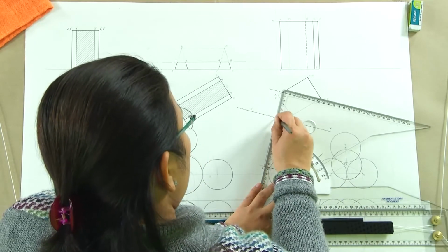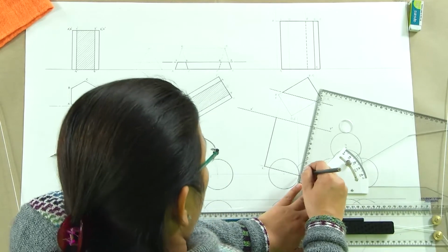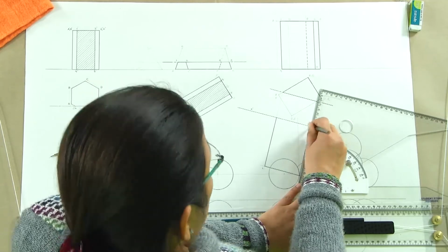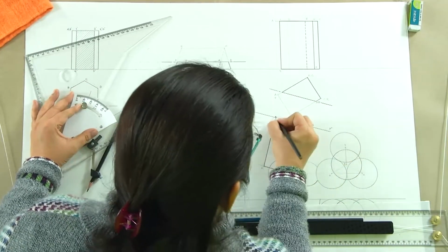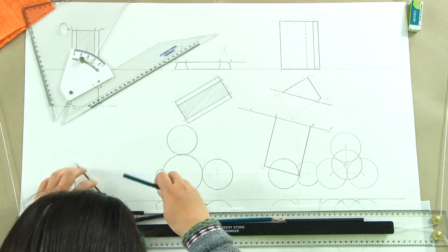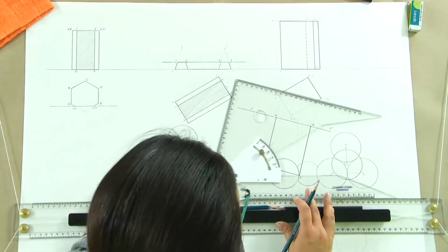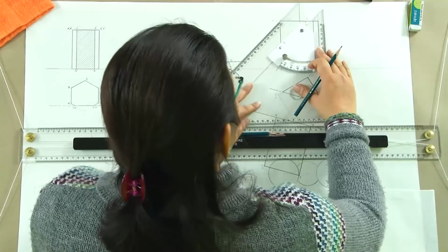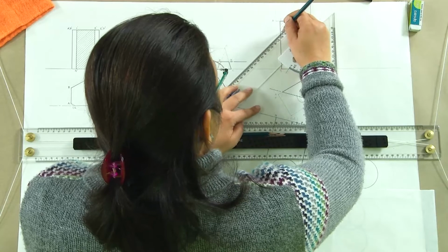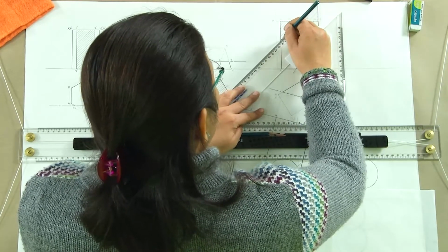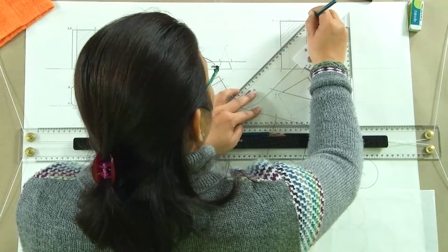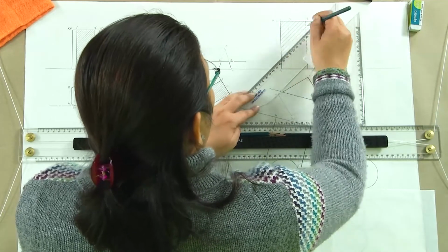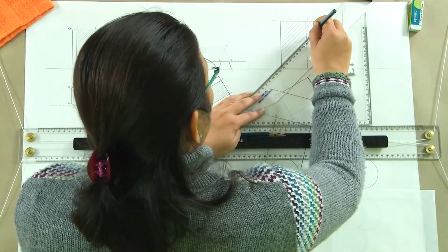this is the true shape of the section. And what do we get here? We get 1, 2, 3 and 4 as the true shape of the section. And before we finalize this drawing, we have to hatch it. So, we are going to hatch it in the same orientation, which is this. I am doing it at a greater spacing, but when you make your sheets, you should try to make this hatch closely spaced, which will look much better. So don't make a hatch which is as far spaced as I am drawing here. Try to make it closer.